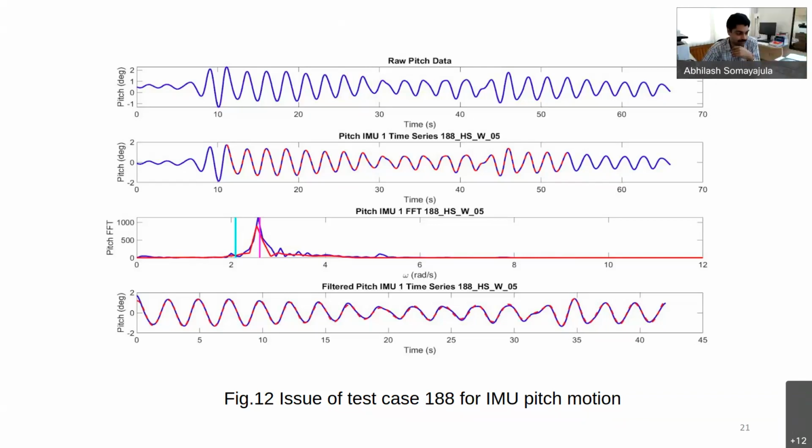My thought process would be something like this. Take the total acceleration vector which you get from your IMU and form a rotation matrix from the orientation. So transform that acceleration vector into the so-called inertial space. Right now it's in a body fixed space, right? The frame is actually moving with the body.